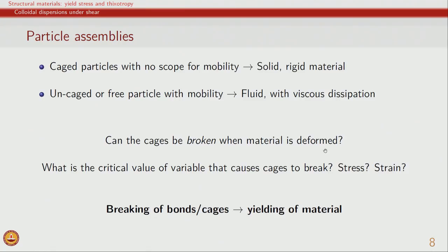And so, we see in this case that there is a yielding phenomenon which is associated with the structure of the material. We are of course discussing fluid-like materials, and in this case the colloidal particles and their assemblies. The colloidal particles are dispersed in a fluid, and this is an example of a multi-phase system as we have been discussing in this course. So, we can say the material yields if it shows a fluid-like response; the material is below yield if the overall response is solid-like.